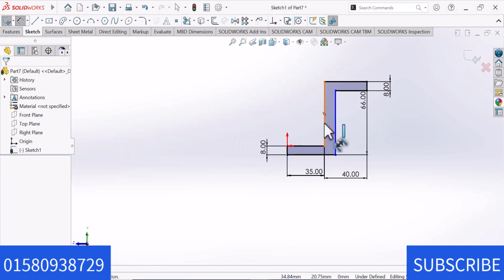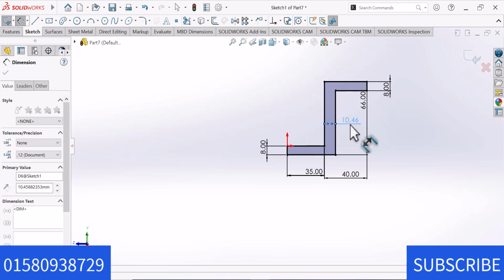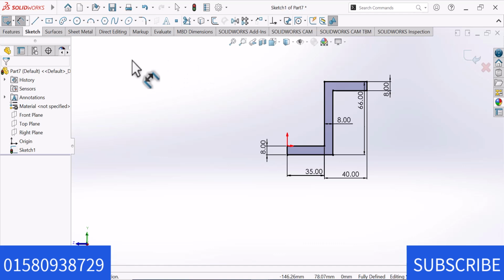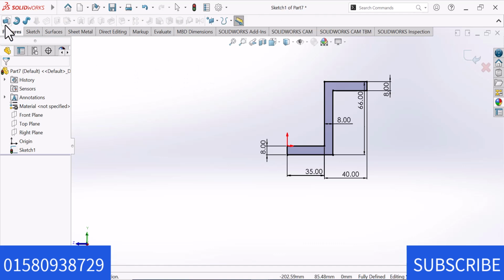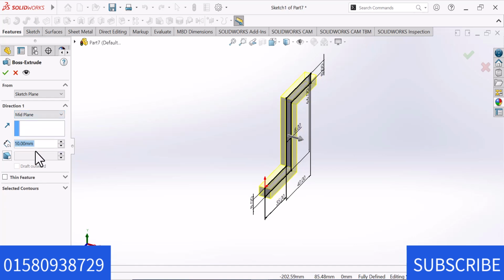And this line and this line distance 8. Okay. Now go to Feature and select Extrude. Extrude from mid plane. Now here give the value 30. Okay.